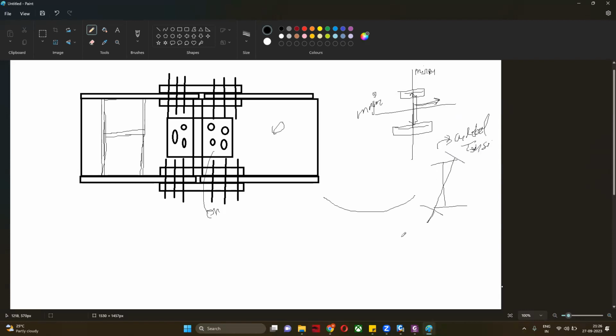But in this, what will happen? If one local buckling also happens, what will happen? All these things will remain the same, but at this location, crippling, or maybe at this web location, this will try to topple, like it will become like this, a bulge. So to avoid this, we require this stiffener. Then if it is still generating, then we provide the longitudinal stiffener.